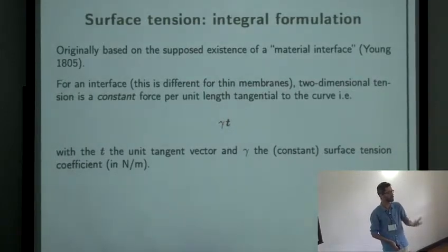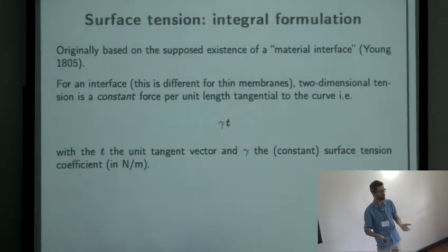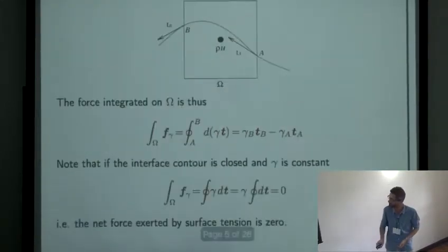And of course, all the trick about these surface tension models is that what you can get from them is a force per unit area, but what you need in the end in Navier-Stokes, formulated in a volumetric way, is a force per unit volume. So you have a missing length scale, okay? There's a problem there, okay?